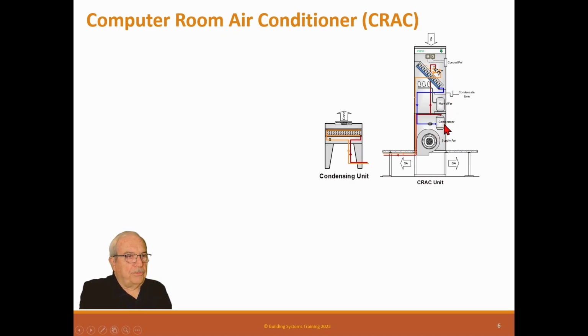Now these are computer room units, so we've got a whole bunch of heat in the space. We never need heating. We only need cooling, and we don't need dehumidification. There should be no reason we'd ever need dehumidification. There's nothing in there that's going to make humidity. Now, if the outside air is so high that you have to have it lower than in here, then you'd have to put a dehumidification system on the outside make-up air to the space and dry the system that way. But normally they need humidification, because we want to see 30-35% humidity in the